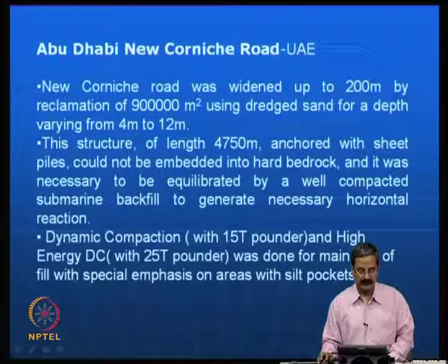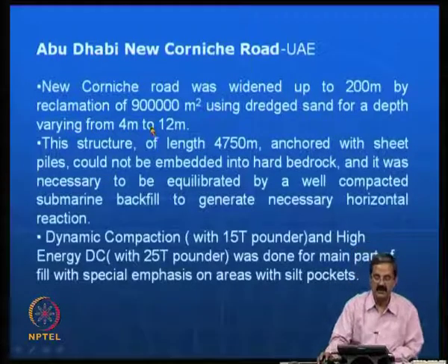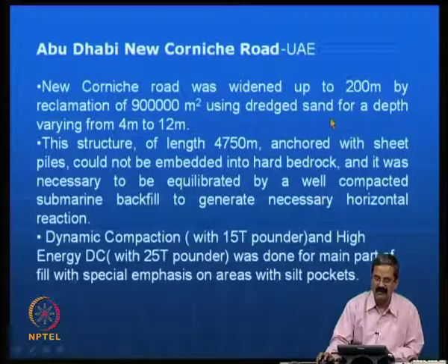There is another one, which is an airport close to a road. The road is widened up to 200 meters by reclamation of about 0.9 million square meters, using dredged sand for a depth varying from 4 to 12 meters. It is a road widening project, so a lot of filling is involved. They got the sand from some places and filled it up to 4 to 12 meters.